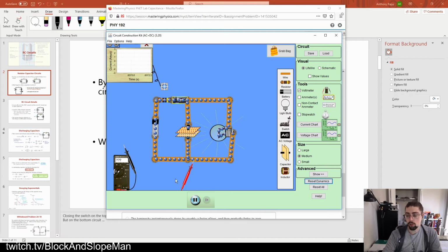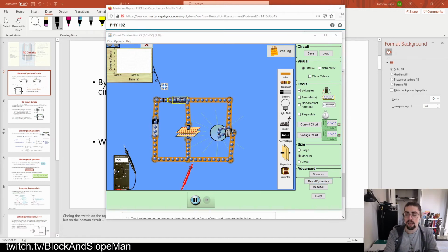The light bulb, on the other hand, at the very beginning, this thing is acting like a short, right? It's acting like a short right between those two points. As time goes on, because current through the capacitor becomes impossible, current along that path decreases down to 0, now all of the charge is forced to go through the light bulb instead. So this could be a fantastic little thing for a charging indicator, for example. Right? When the battery is providing that strong voltage, when everything's all set on your capacitor, maybe it doesn't have any current anymore and the light turns on.